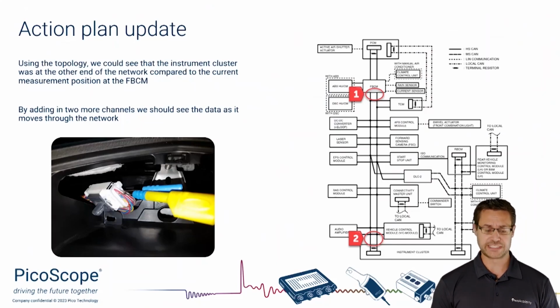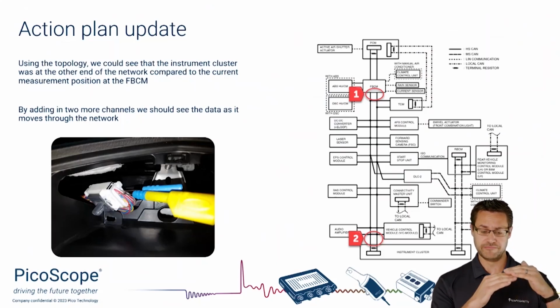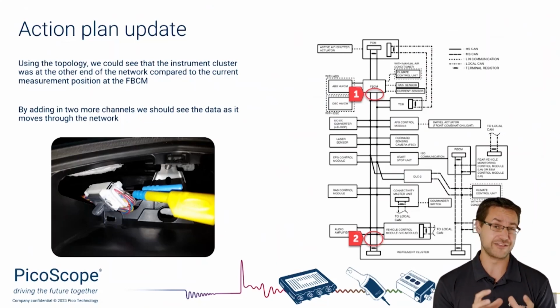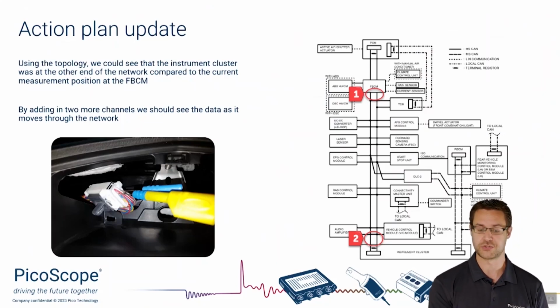So what does that tell us? Well, clearly we've got a problem. It also means that the only way that you could particularly have shifted packets, especially between CAN high and CAN low, is if there's something physically wrong with the line or the communication line. It's not like an ECU is corrupting the data as such. Something has shifted. So how can we prove that?